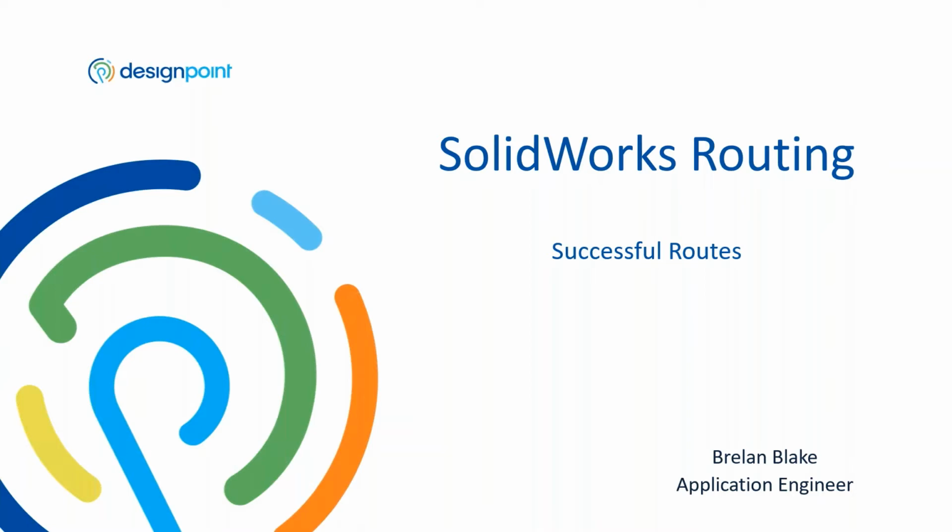All right, so the first thing, like we just talked about here, the first option, you do your file save as your existing route components. You'd go to your design library, which I show here on the right-hand side. Notice the file structure as we're going through piping. You have various options underneath piping in your design library, and your design library is going to be constructed of all your disciplines, and everything is organized from your standard installation. And you can utilize some of these components as a drag and drop option into some of your assemblies to begin your route. These components are already defined and already processed through the routing library manager. So these components in your design library underneath routing are already ready to use, ready to route.